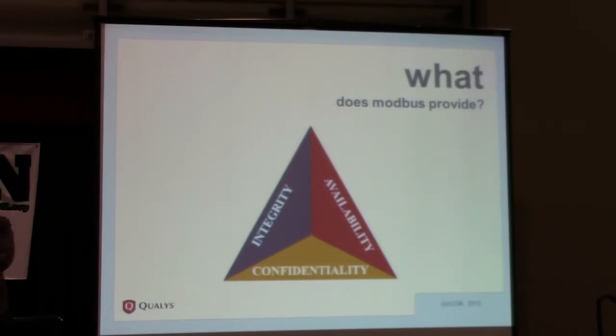In Modbus it's mostly based on polling, because the client says, okay, give me this, and it has to poll a lot of times. In DNP3 you could have sort of a callback mechanism where you can say, let me know only if the temperature changes or if the pressure changes or whatever, and then you get notified automatically. And it has a lot of other improvements on Modbus as well.